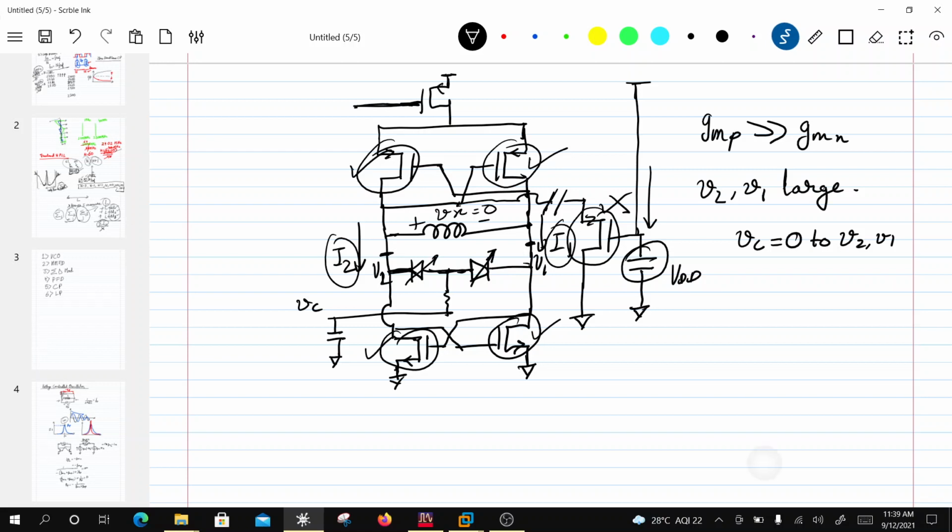If I choose a smaller NMOS, that would mean I can have a larger voltage across the device, and the capacitance of a reverse bias diode is going to be like this. It is going to go up to a point where the device turns on. At that point it will reach the maximum and then it will drop off. So this is basically what the capacitance is doing.